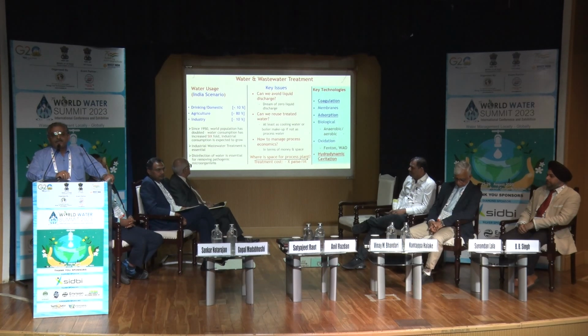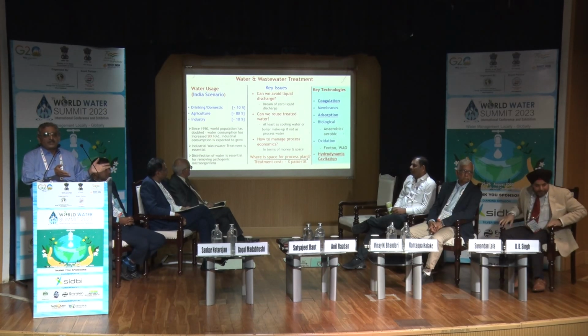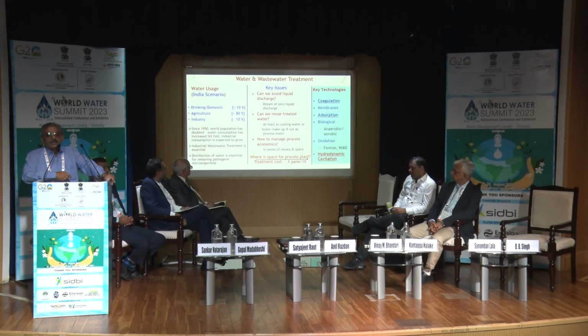Now the most important question in water recycle and reuse: why are people not doing it? The earlier speaker showed that we have only 10-20% recycle and reuse on average. Why are people not doing water recycle and reuse when it is possible? The main reason is how to manage the process economics. In terms of money and space, like the earlier speakers have shown, biological treatment processes require huge spaces, okay? And in places like Pune, Mumbai, Delhi, where is the space available? The cost of treatment per meter cube of water is another concern. So you need to manage the process economics.